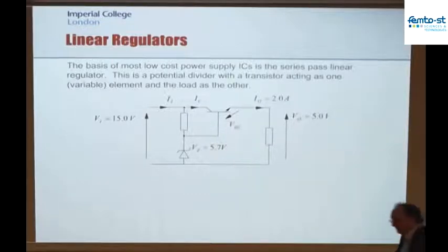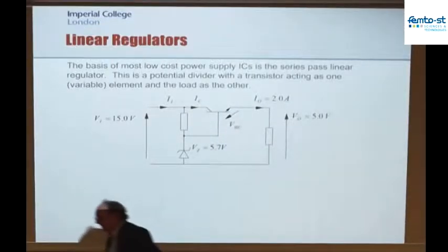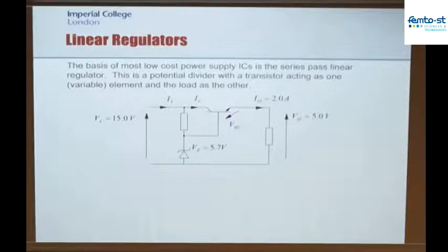Certainly, as I said, my laptop computer in this case takes 18 volts on the input, which is fine. But of course the processor doesn't use 18 volts. The screen actually uses a lot more than 18 volts for the backlight. So clearly when 18 volts comes into the laptop, some of the power needs to be stepped up to a higher voltage, and some of it needs to be stepped down to a significantly lower voltage.